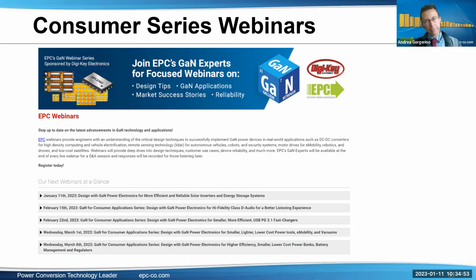Okay. Next question is, what kind of process are you using on your GaN ICs? Is it CMOS or BiCMOS for logic and GaN for the power MOSFET? Single die, or is it hybrid? They are actually all GaN. There's a little picture here. This is one of our first ones that we did. These are the FETs, and this area right here, that's basically the GaN IC. So it's monolithic. It's all made in GaN. So it's GaN IC technology.